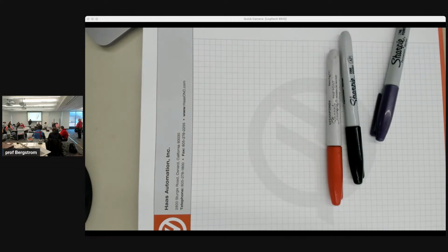Who in the class has ever hit the emergency stop button on the machine tool? Well, that's a lot of you. Why did you hit it? Sometimes they told us to, when we finished running the program. All right, so you used it to end the operation of the machine. Yeah, to make sure you were finished, and you hit the e-stop button before you walk away from the machine, so that if somebody else wanders into the machine shop and inadvertently presses a button, it doesn't start an automatic operation. That's the reason we tell people to use the emergency stop once they're done with what they plan to do.